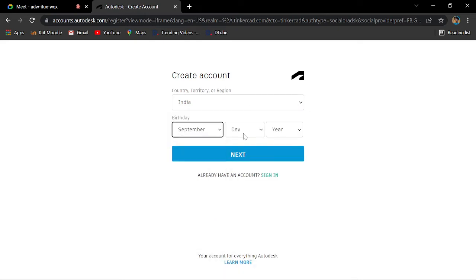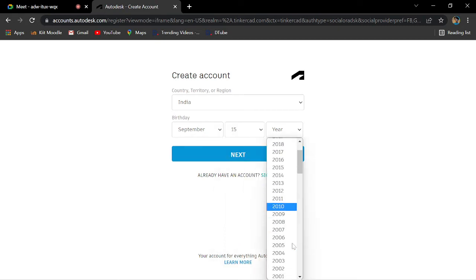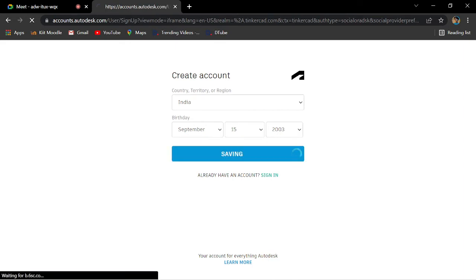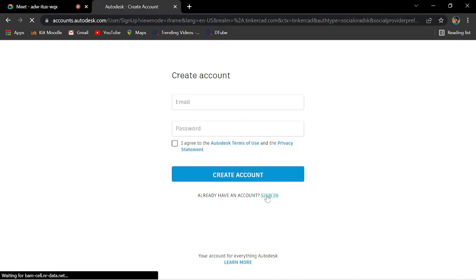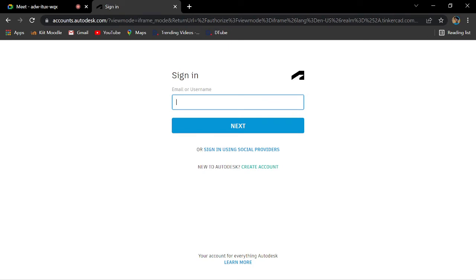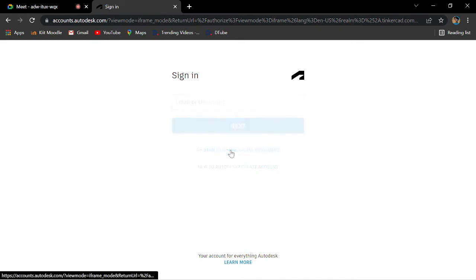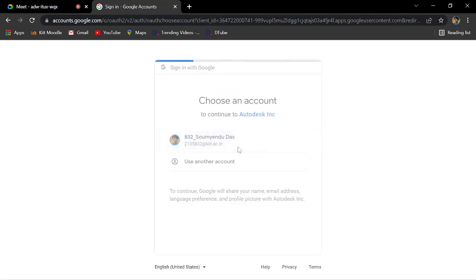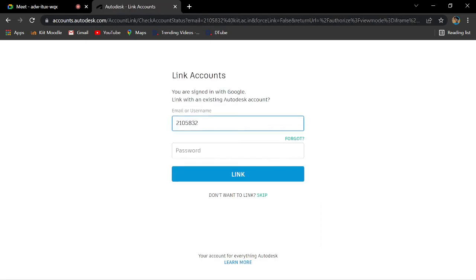Acha, this is an important thing. This is a multimeter. You guys have heard about voltmeter, ammeter. Yes, sir. So, okay, a voltmeter has to be connected in parallel with the circuit. An ammeter has to be connected in series with the circuit, and an ohm meter is used to measure resistance. But a multimeter can be used as an ammeter or a voltmeter or an ohm meter. Okay, so it has a fixed negative and positive terminal.